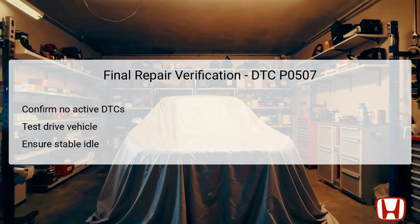To verify that repairs related to DTC P0507 have been successful, first confirm that there are no active diagnostic trouble codes remaining in the system. Next, conduct a test drive under various conditions to ensure that the vehicle operates normally. It is essential to monitor the engine idle during the drive. It should remain stable, without oscillation or elevated RPMs.